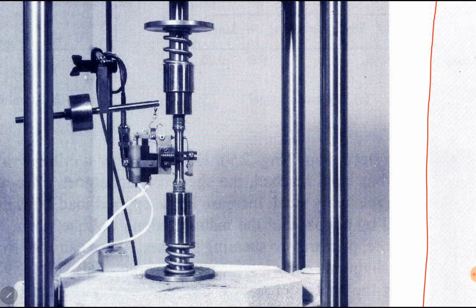And the vertical axis shows stress S in KSIs or megapascals. So these graphs are SN curves for steel and aluminum. This graph shows failure values, the values of stress at which material will fail at some specific number of loading cycles. For example, at 10 power 4 number of loading cycles, the aluminium 2024 will fail at this value of stress, which is around 44 or 45 KSI.